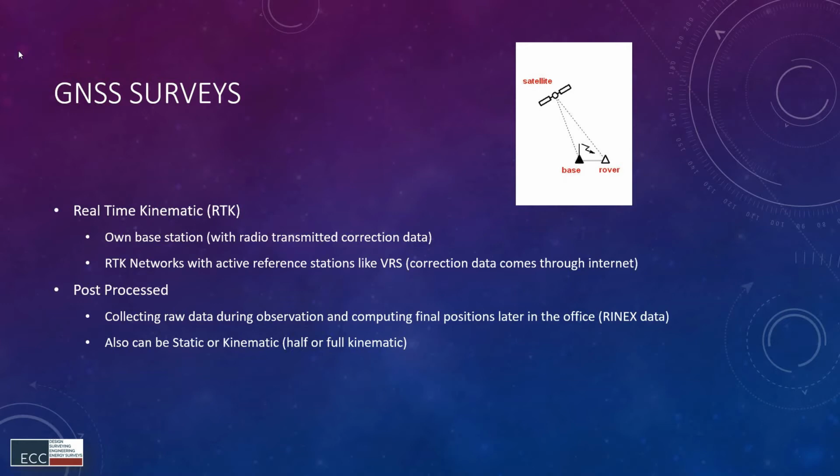For that one, I would leave our base for maybe 2-3 hours, definitely at least 2 hours. And with your second receiver, if you want to go around and observe more control points, it's really based on how far you are from your middle point of observation. If you are about 1 or 2 kilometers away, a half an hour would do, definitely no longer. If you go farther, maybe 40 minutes, 45 minutes.